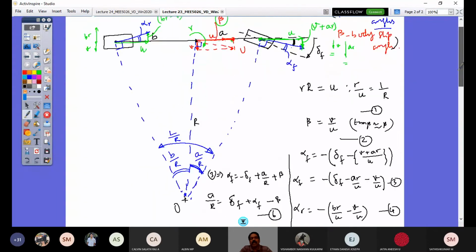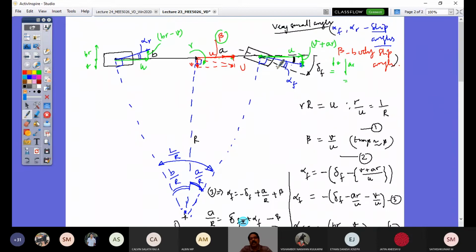This is essentially given by this configuration diagram, wherein we were able to represent the motion parameters, effect diagrams, you can say. There are no forces represented here. It is only the motion parameters. That's why it's called a kinematic diagram. And this angle at the center of turn is L by R. So the angle subtended by the wheelbase at the center of turning radius is L by R, right? And this essentially is the sum of A by R plus B by R.